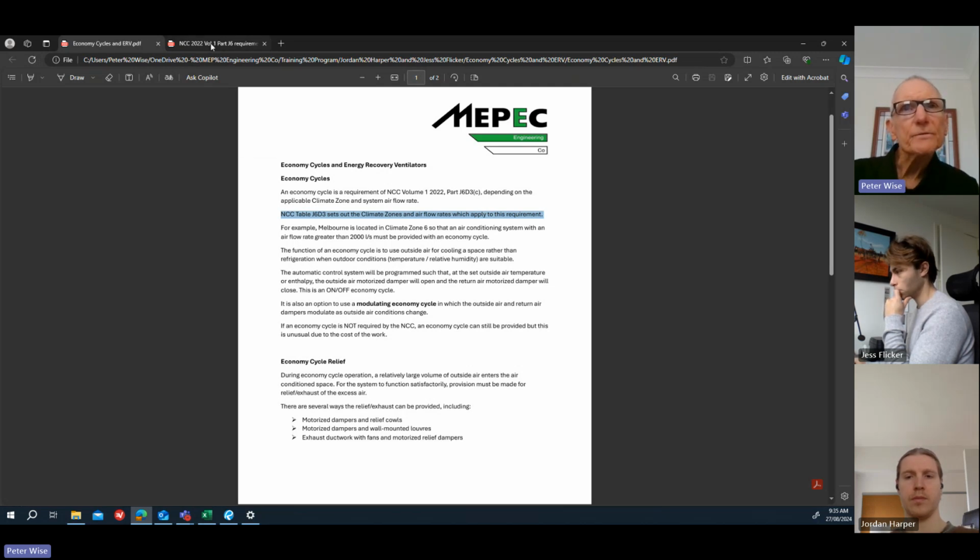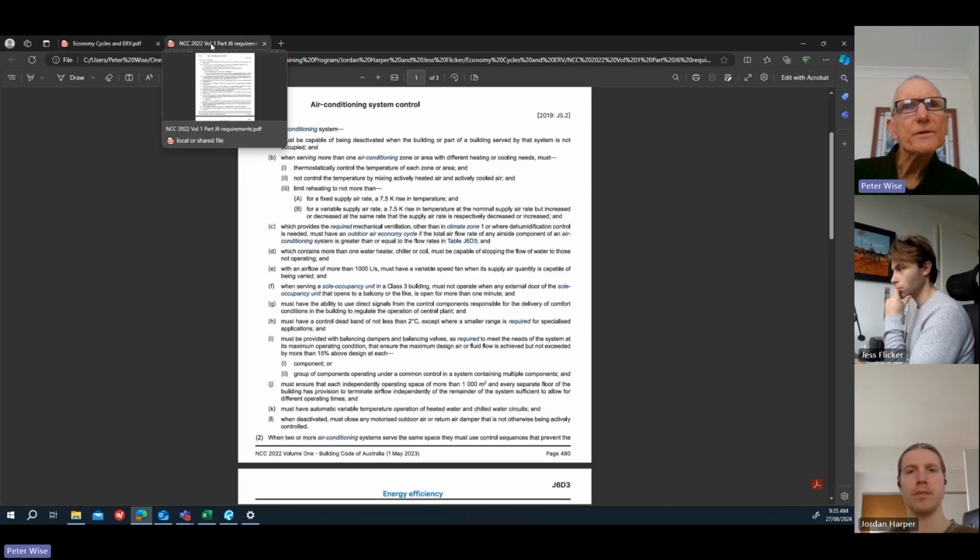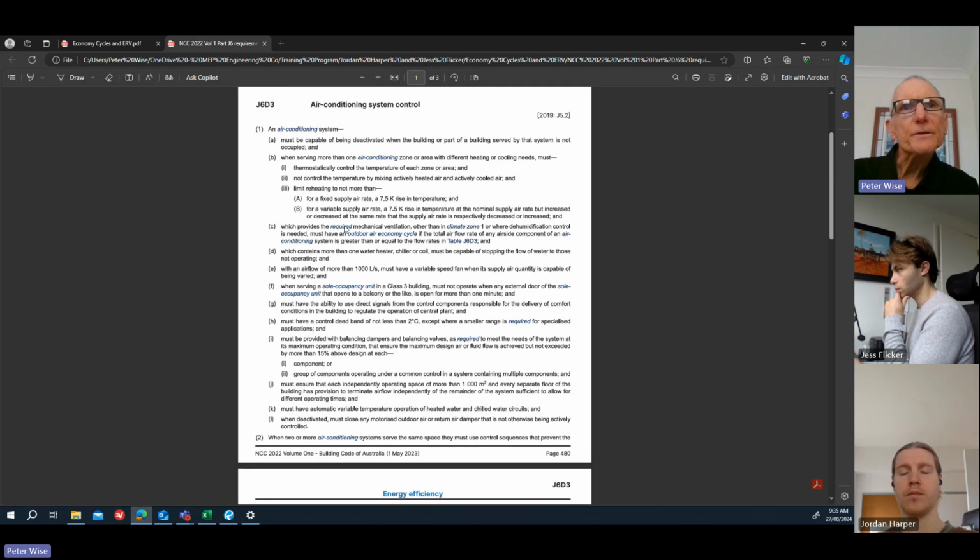So just to show you the NCC, so J6D3C. C, an air conditioning system which provides the required mechanical ventilation, so which means it's bringing in outside air as well, other than in climate zone 1, or where dehumidification control is needed.